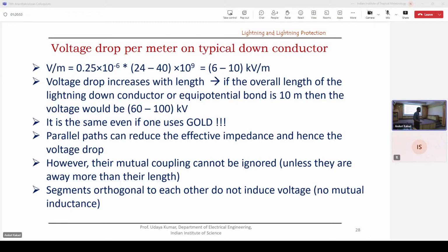And man, this cable impedance is defined for what is called the transverse electromagnetic mode of propagation. That is, you inject equal and opposite current in the core and sheath. That is the cable mode of operation. In every section, total charge and current is 0. That time you measure what is called impedance for the transverse electromagnetic mode. Where is the opposite current in practical lightning? There's no opposite current, only one flows one way. There's no closed circuit whatsoever. So this was another concept going on. And for that matter, I want to stress one more thing. The cable has no meaning whatsoever.